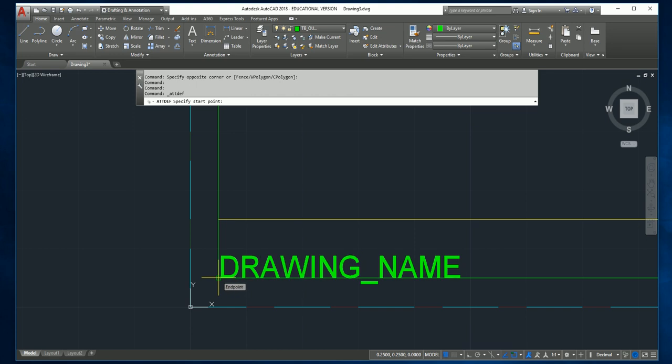So we're going to go ahead and just place it at the bottom corner, the quarter by quarter corner for now. We're going to move it right now. Can we put a specific location? You can, yeah, but I want you guys to move things too, so I'll teach you. You can enter a coordinate, and it's basically left justified because that's what we left it as. If we put center, it would do the center justification, things like that, which you could always modify in properties too, which we will show you.